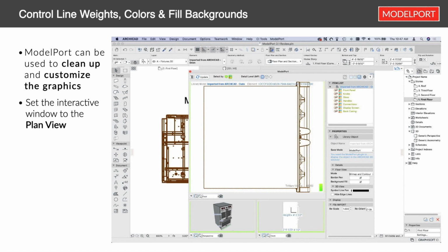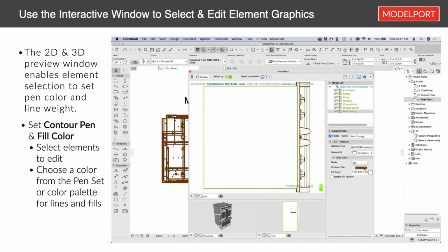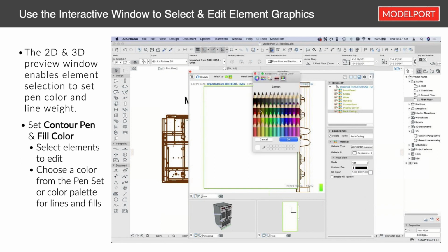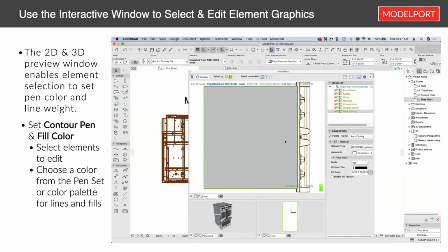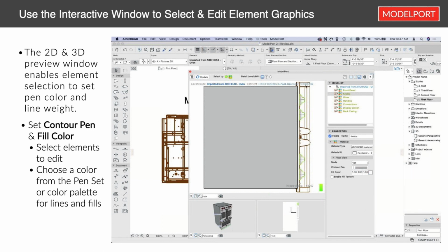I'm going to come back to that in a second in terms of how we might work with that. The next thing we want to do is reduce the polygon count. So I'm going to select all the meshes in my model here, and then select the panels that I don't want to reduce the polygons on. For example, the front panels here, I do not want to reduce those because it would triangulate those flat surfaces.